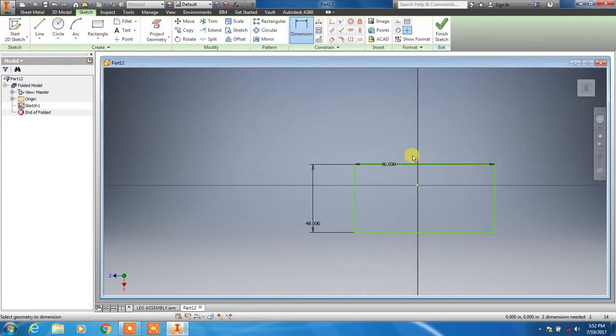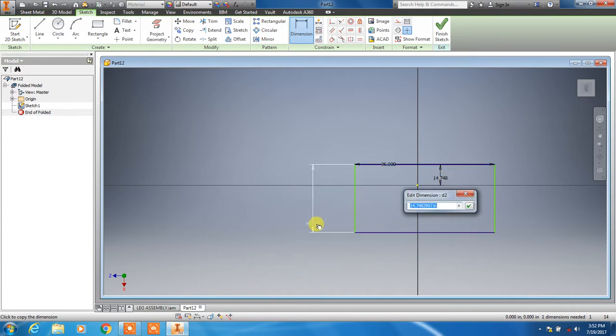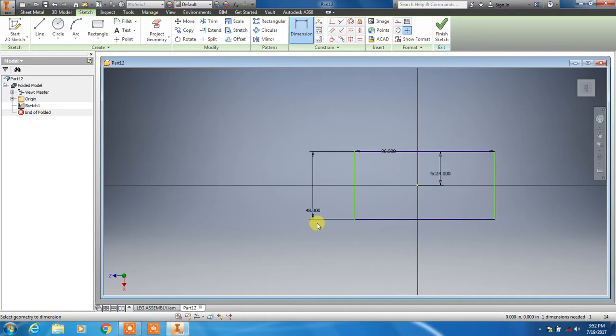I hit the wrong button. So from there to the center of the page, we're going to click and we're going to tell it to make it half of that. So that way if I edit it and I change this to a 5 by 10 table, I only have to make 2 changes. And then we're going to do this one the same way. That one divided by 2. Enter. Okay, we're fully constrained.